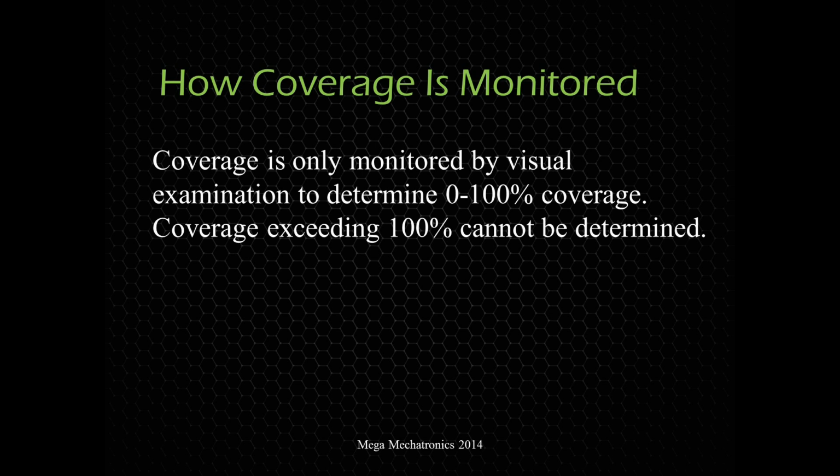But that's not really the best gauge or the most optimized method, because a piece of shot could hit the workpiece at a low angle and deflect and not really impart residual stresses. However, it may be enough to scrape off that coating. So it could give you some false positives there.